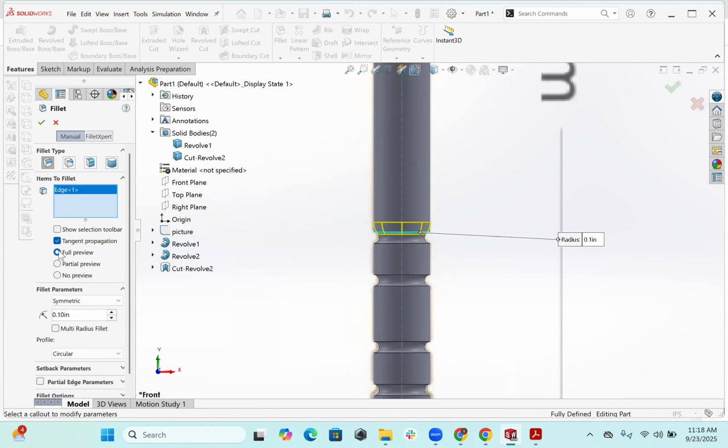This should be much smaller. So I'm gonna just pick faces. Each face that you select, it connects to two edges, so it will automatically do those edges. I can also pick this internal faces. So I'm basically rounding everything together.